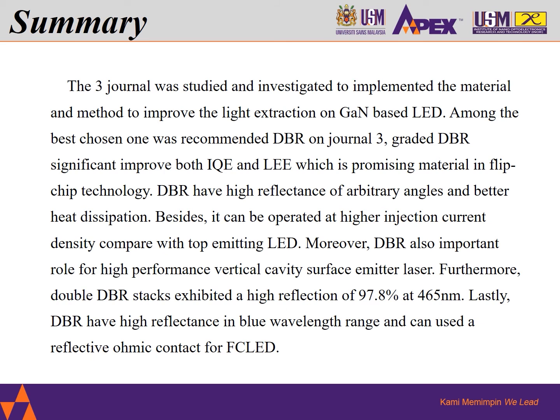As for the overall summary, the three journals were studied and investigated to implement materials and methods to improve the light extraction of GaN-based LED. Among them, the best chosen one recommended is DBR in journal 2. DBR significantly improved both IQE and LEE, which is a promising material in flip chip technology.